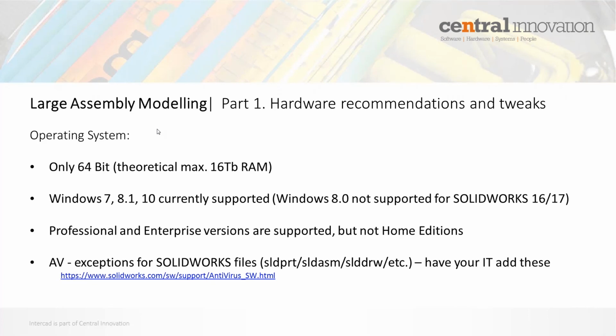Antivirus exceptions. Sometimes antivirus, particularly if you're working across a network, can block, or it can check your SolidWorks parts as they're coming across from the network to your local system when you're opening them in SolidWorks. I'd probably suggest that you have your IT admins add these as exceptions. SolidWorks haven't identified any specific viruses which target those files, and so you're probably relatively safe in bringing those across as exceptions when you're opening them up. And that should improve performance, because sometimes these files will get caught up in AV systems. You won't notice it, it'll be a bit transparent, but it will actually slow down the opening process.